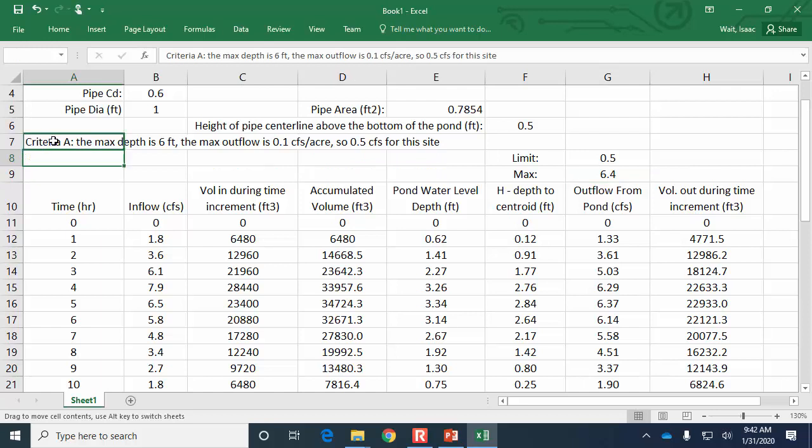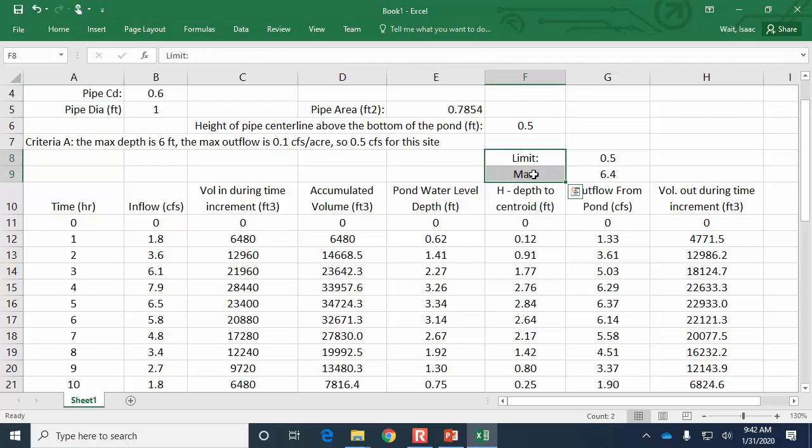Let me drag this up. You said the numbers between on the outflow pond, correct? Pardon me? On the max equation, what did you select? The outflow, because our design criteria is that we're limited to 0.5 CFS. So it's the outflow.